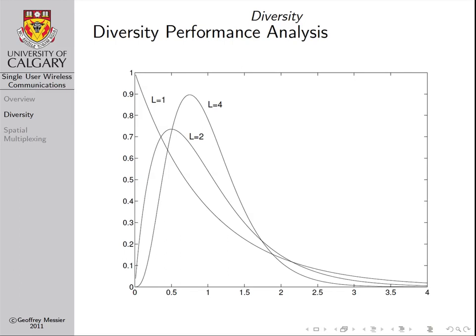For example, if we're talking about antenna diversity, to go from 1 to 2, we had to add a second physical antenna and a second dedicated receiver for that antenna. That hardware costs money. When we go from 2 to 4, we had to add 2 antennas and 2 dedicated receivers for not quite as dramatic an improvement.